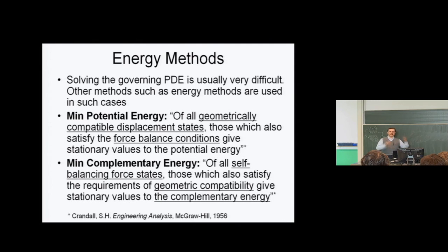And I was quite good as a master's student and undergraduate student. I had gone to a good university, so I was a bit upset and disappointed that he could just by looking say that the results were wrong. And he said, go do something and don't come back until you fix it. It took me a week and I had to go through a solution like this, which was approximate, but at least showed me, first, my boundary conditions on my finite element model were wrong. And second, the way I was applying the loads, I was presupposing the displacement pattern, which was not necessarily correct.